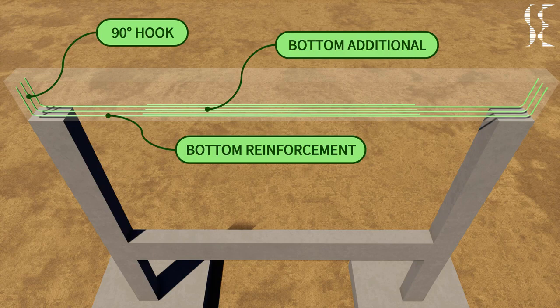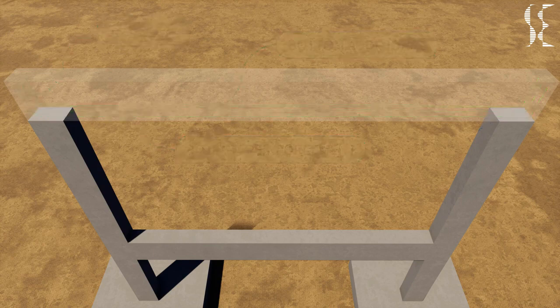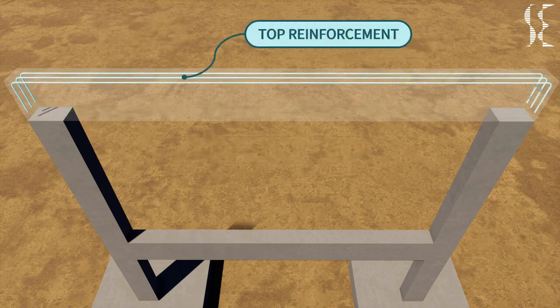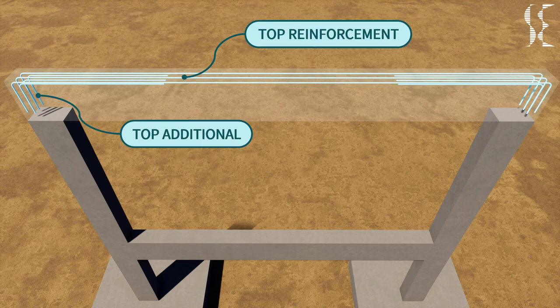Then comes top reinforcement, which runs from column to column and has a 90-degree hook with sufficient anchorage at the ends. Top reinforcement also resists the bending stresses produced at the supports. In case additional reinforcement is required by design, they are provided as a second layer below the top layer and are extended by 1/4 of span length from face of column or as required by design.